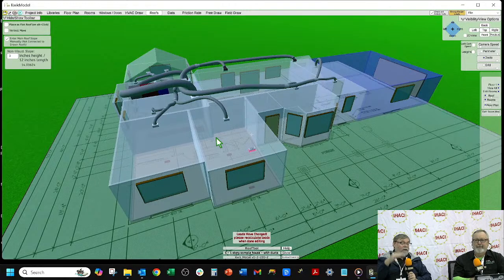You do not know how many times I've done load calcs. Guy has a 4-ton unit on a 1,500 square foot house, and I go into the load calcs and say, no, you don't need 4 tons. You need 2.5 tons because you've got new windows, you've got new insulation. Yep.